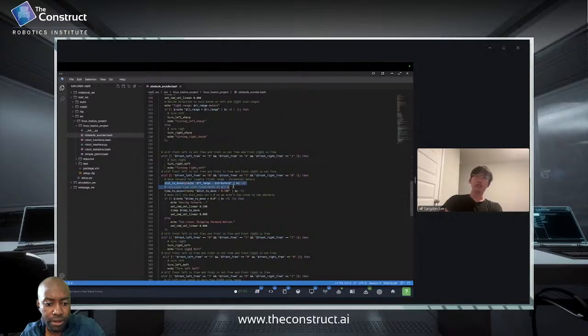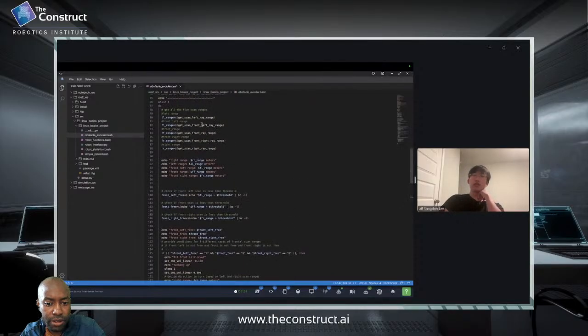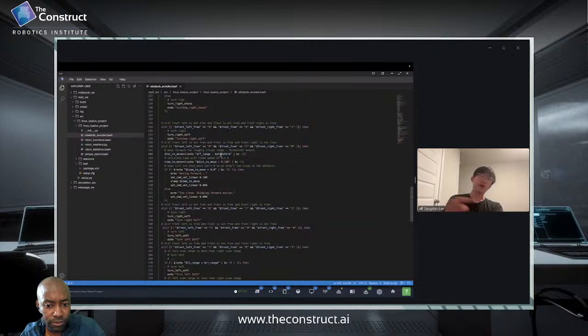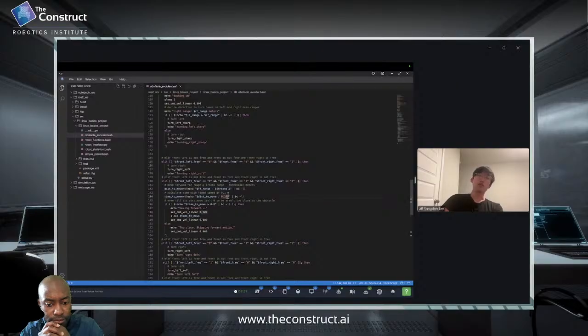We have to use this distance because we already set up the variables up here for the different ranges like left, front right, and right range. And we get the distance to move, and we subtract the threshold, so we know how much distance we had before we hit the threshold. And then since we are moving at 0.1, actually you should change that to 0.15 if you want to be specific here. But you're saying that we want to move 0.1 meters since that's what we set up as a linear speed, and you divide that to see how many seconds we want to move.